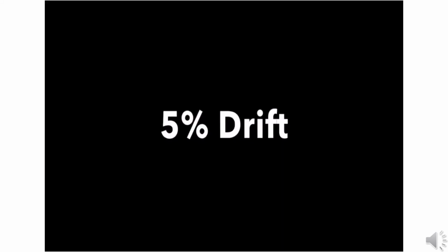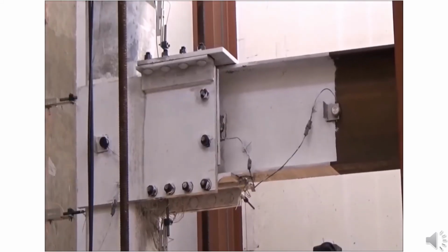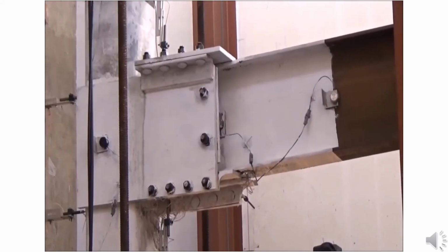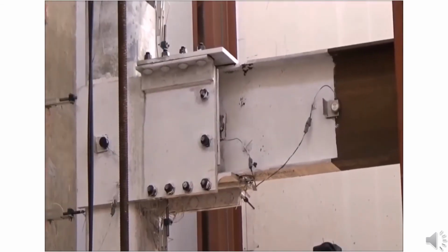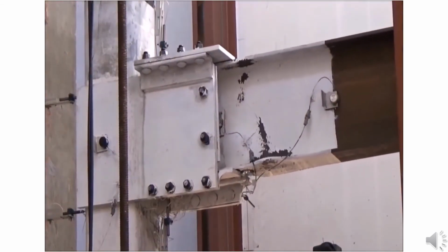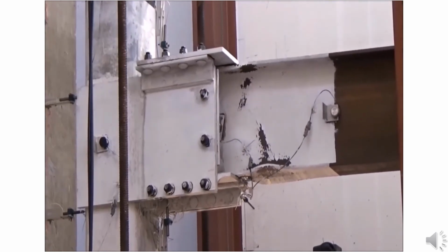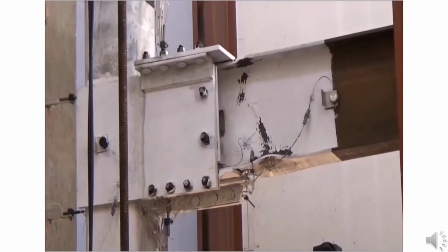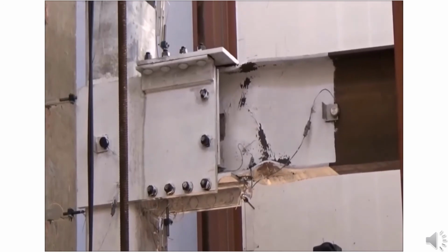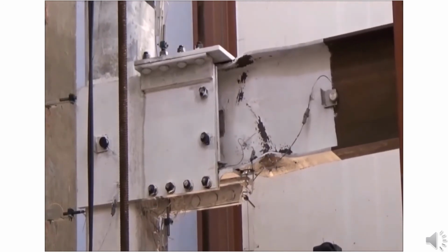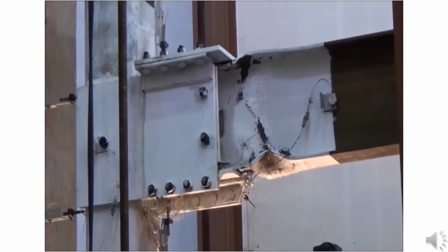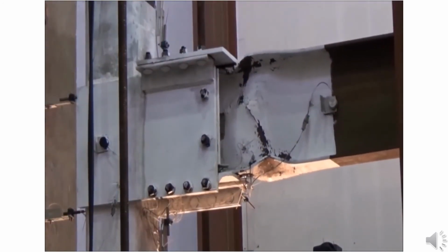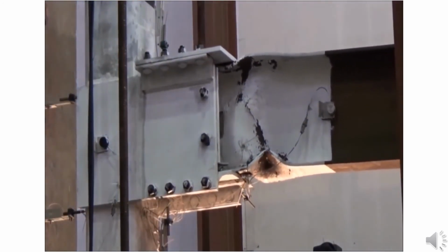Since SidePlate moment connections are proportioned to develop the probable maximum moment capacity of the beam, the plastic hinge formation occurs within the beam. The side plates, in particular, are designed to develop a moment capacity larger than the plastic moment capacity of the beam. This is done to push the yielding and strain hardening towards the protected zone of the beam.